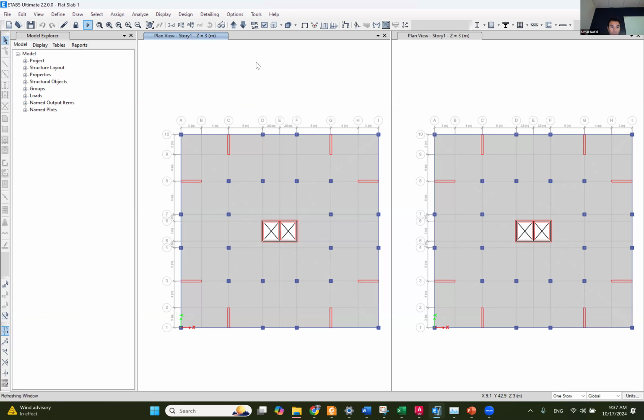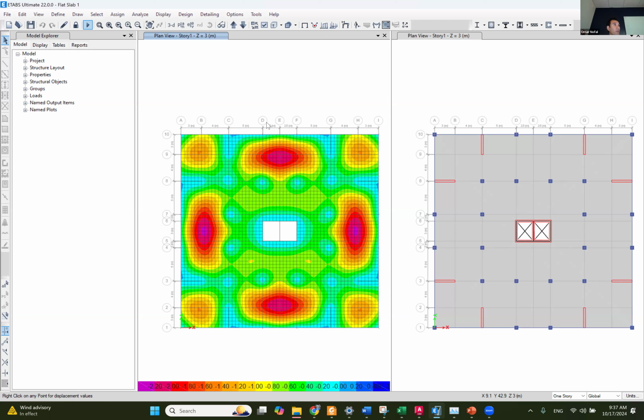All right. Okay, can you see? It becomes rectangle, looks much better. Maybe if you want, you can check the deflection in the middle, with the 1 meter mesh and the 0.5 meter mesh, regular or not regular. So you can check how different it is. There will not be much difference, but you can try.